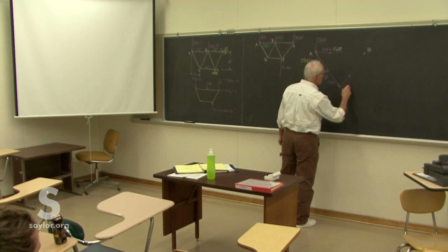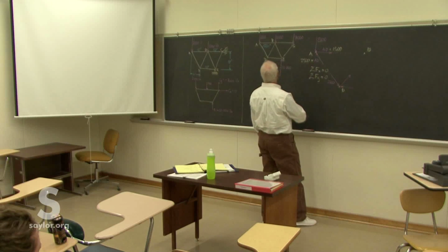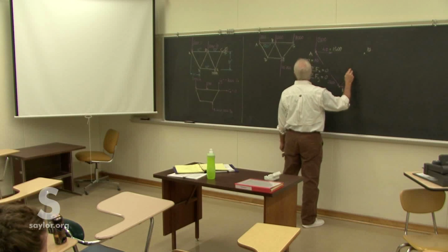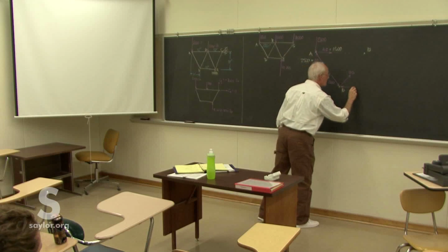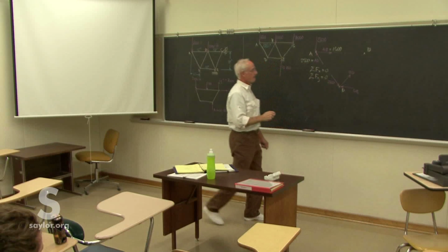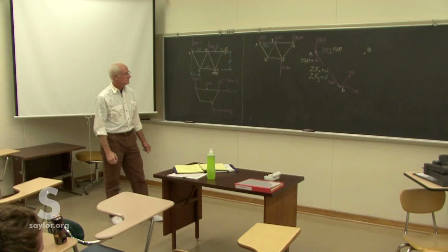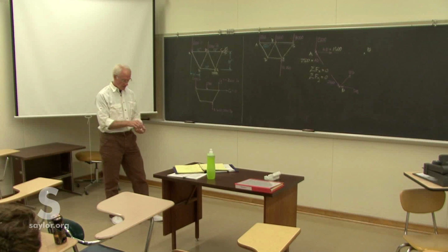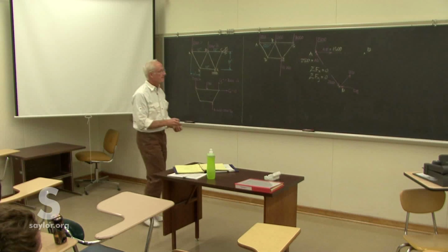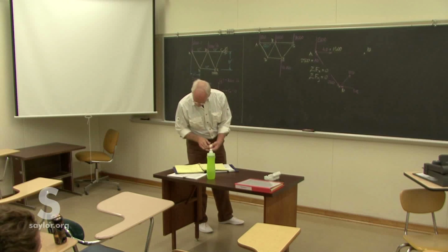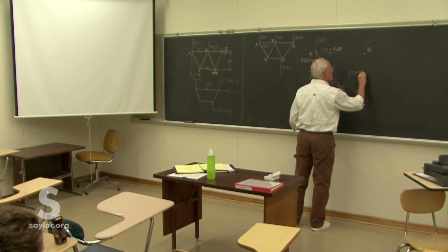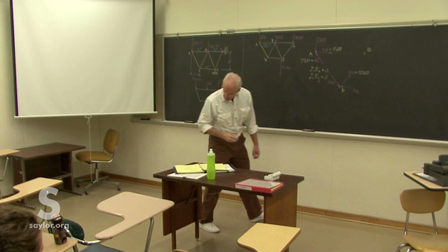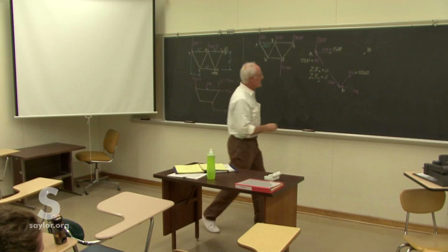And since that's one going to the right, that one must go to the left. And we can label these. This is DD, and that one's DE. And we can solve for those two. Comes out to be, this one's also 2,500 pounds, and DE is 3,000.